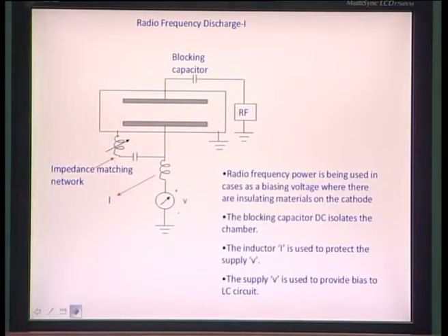So the RF discharge or the radio frequency discharge mostly happens because instead of giving a DC bias here, you are giving an RF signal. So there is a tendency of both the electrodes to change polarity cyclically as the RF frequency is programmed at a certain frequency, okay, at a certain occurrence rate. So in one half cycle, let us say you have a sine wave as the signal, this side will get a positive charge, this side will get a negative charge, and in the other half cycle this would interchange. So this becomes positive here and this becomes negative here.